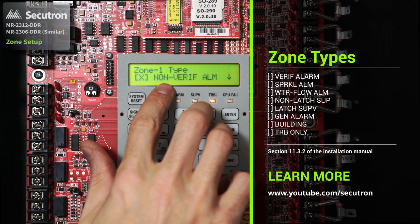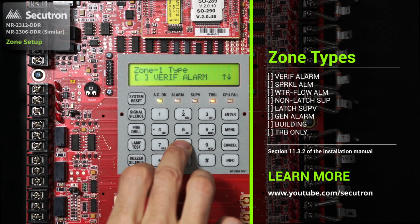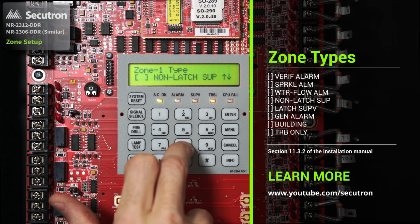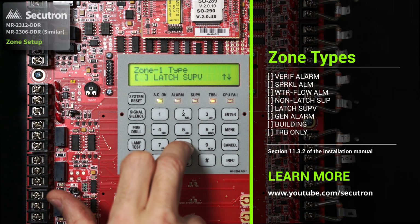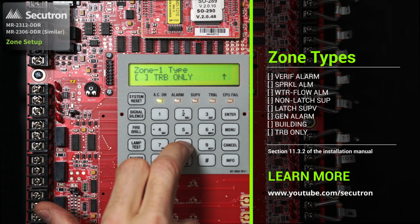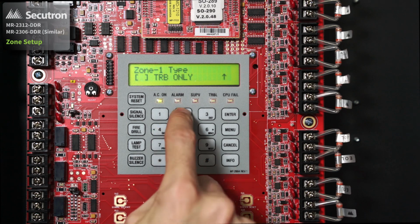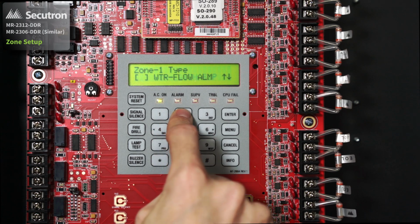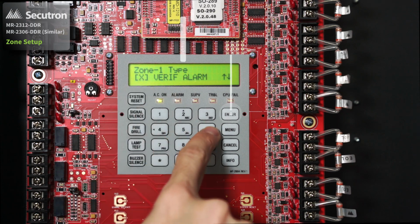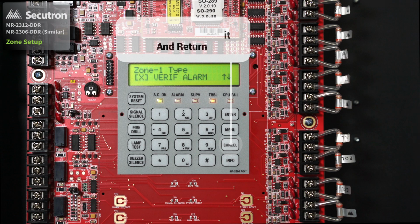By default, it has been selected as a non-verified alarm, but we could have it set to a verified alarm, a sprinkler alarm, a water flow alarm, a non-latch supervisory, a latch supervisory, general alarm, building, or trouble only. Once the desired selection has been located, we can hit the left or right cursor arrows to select what we want. So if we wanted a verified alarm, hit the right cursor arrow, apply the X, and we hit enter. Zone 1 will now be notified as a verified alarm zone.